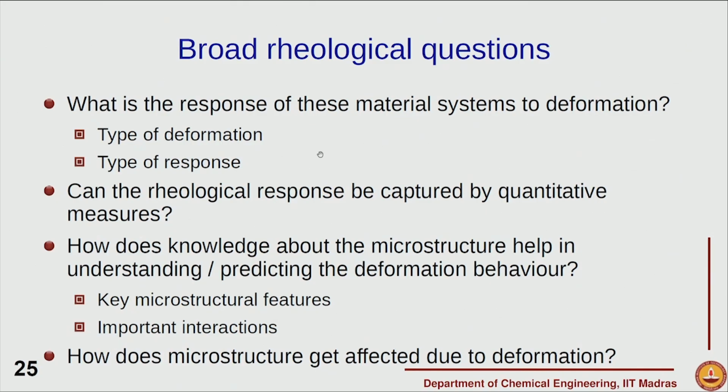As opposed to a Newtonian fluid where a viscosity as a single constant characterizes the overall flow behavior, we will see that there are several quantitative measures which can be used for complex materials such as macromolecular and multiphase systems. And so, the next set of questions are related to how we can use the microstructural knowledge in understanding and predicting the deformation behavior. Also importantly, when we talk about eating of curd, due to the deformation being imposed either while using it, serving it, or in terms of eating it, the microstructure is continuously getting modified, and therefore, in the end what we feel as its mouth feel depends not just on the deformation, but also, since the microstructure is getting affected by deformation, these are closely linked. So, we need to know microstructure at rest, but we also need to know microstructure under deformation.